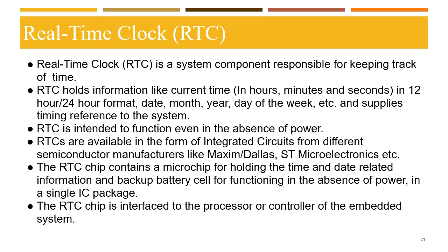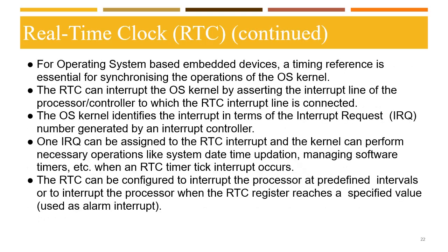The RTC chip contains a microchip which holds the time and date related information and a backup battery cell for functioning in the absence of power in a single IC package. The RTC chip is interfaced to the processor or controller of the embedded system. For operating system based embedded devices, a timing reference is essential for synchronizing the operations of the OS kernel.